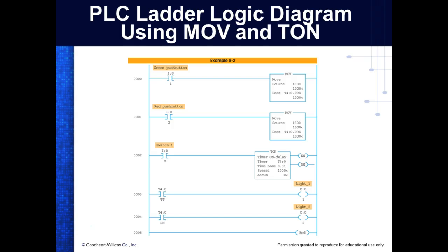Now, can y'all see the address there? So let me make it bigger. This address right here, they're saying T4, so that specifies a timer, right? Then they're putting colon, timer number 0, and then they're putting a dot, which means what follows is a word, because the preset register is a word, right? Y'all understand? So if you put slash preset, then you're going to get an error on that rung that you can't clear, right? Until you say, I'm going to load this word out there.